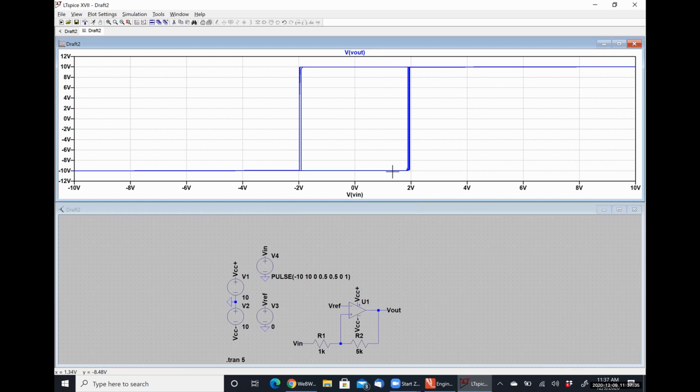All right, so we have this funny rectangular shape. This is what's called a hysteresis loop. Anytime you have an input-output relationship that involves hysteresis, that means the system effectively has memory. So this is telling us exactly where the upper and lower trigger limits are because we can see the output switch. Whenever we get higher than 2 volts, it switches to high and continues going. And when we back down, it doesn't go low until we exceed -2. So as it cycles, it goes like this, over and over again.